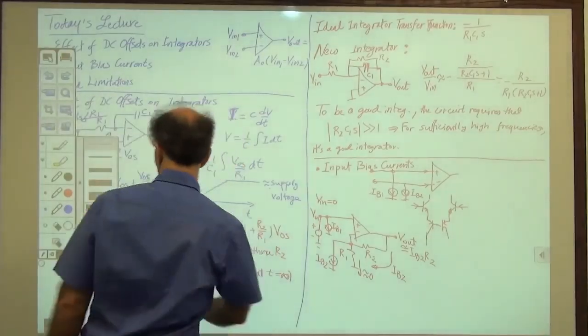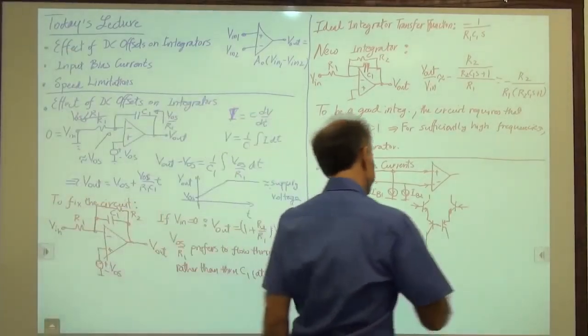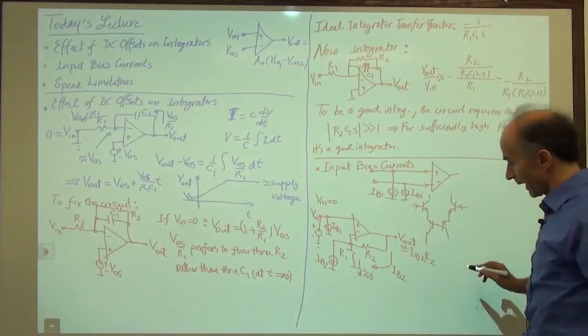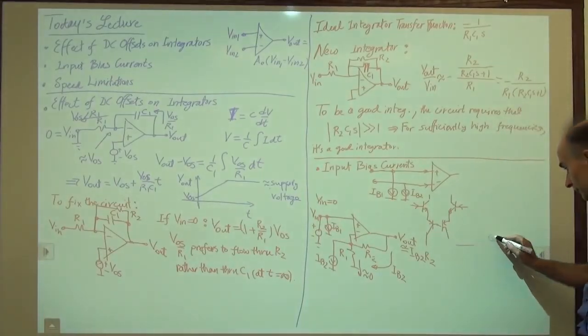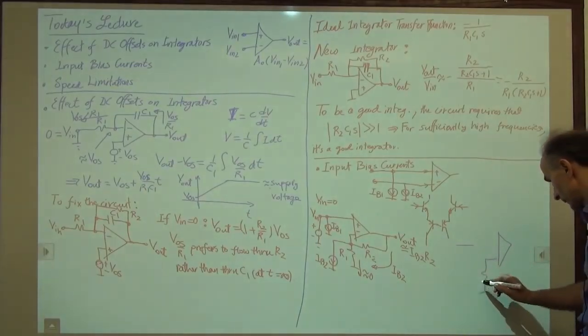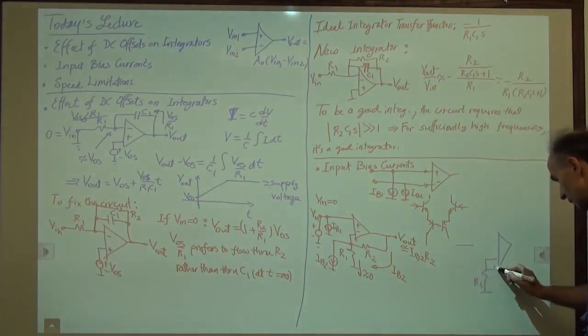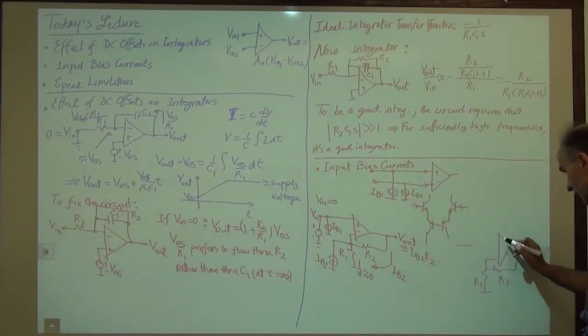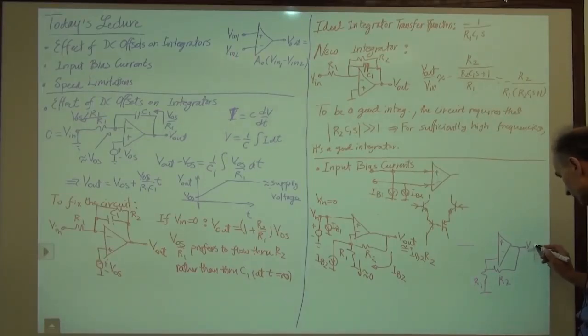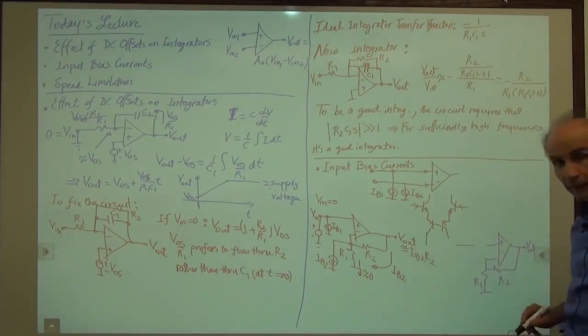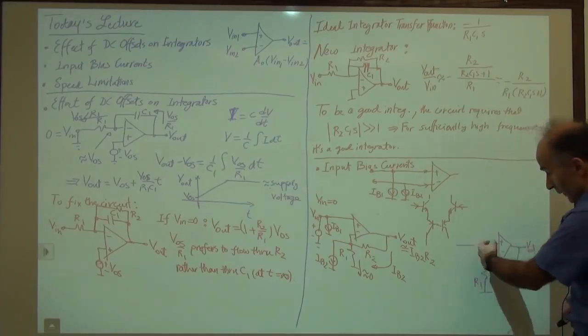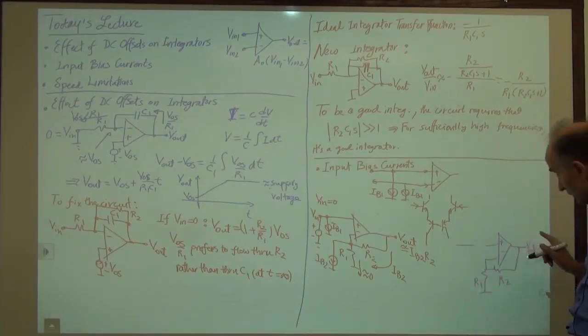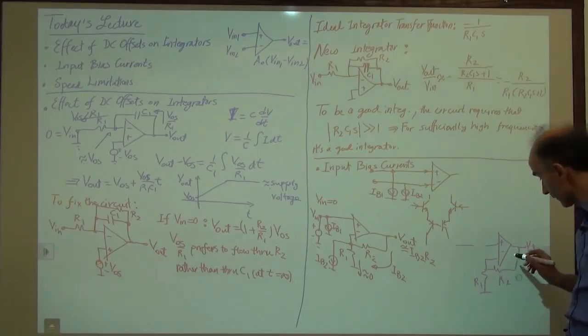So let's go ahead and do this. We redraw the circuit, and this time, this is what we do. We still have all of that stuff, R1, R2, positive, negative, V out. I'm trying to generate a voltage in series with this input so as to cancel the output, so as to null the output.